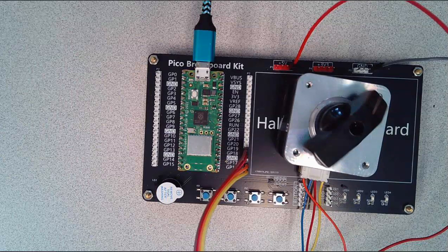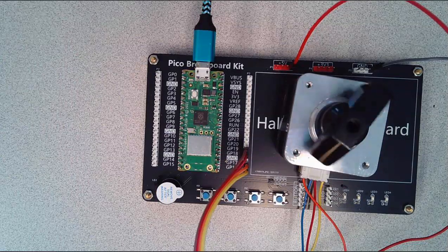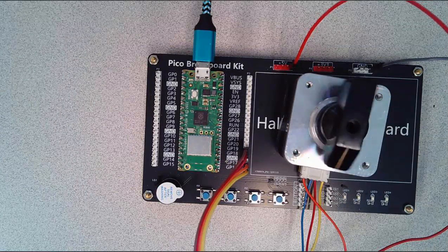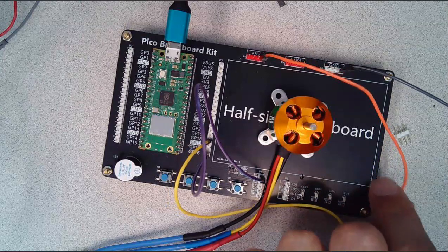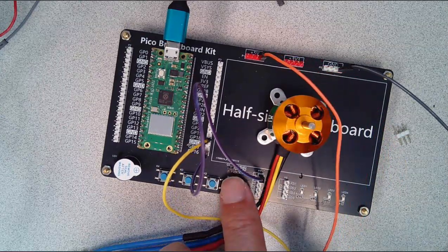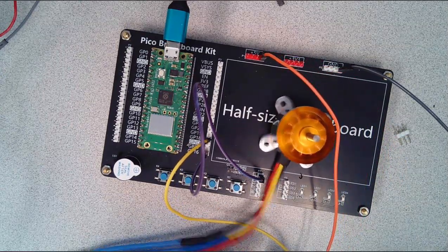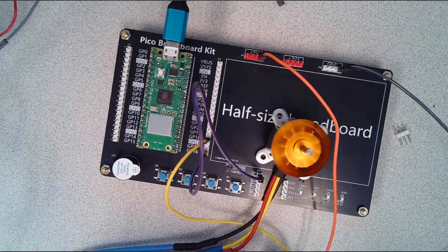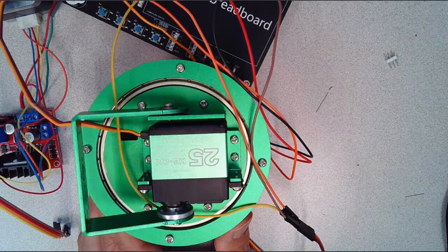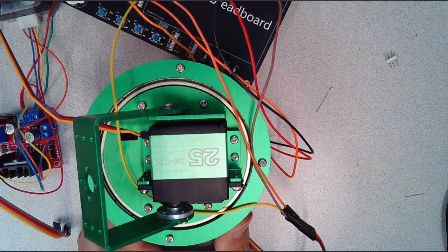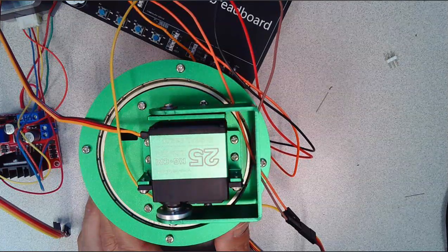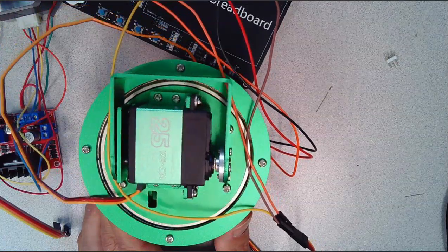The first type of motor we'll look at is a stepper motor. Here you specify how many steps the motor is supposed to go, and you control the position. By controlling steps per second, I control speed. The second type of motor is a BLDC motor. That's a quadcopter motor. If I control the pulse width, I can control the speed of the motor. Third type of motor is a digital servo motor. By specifying the pulse width, the Pico board can control the angle of the motor.